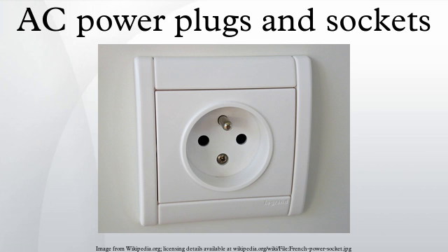Brazilian standard NBR 14136. Brazil, which had been using mostly Class II Euro plugs, and NEMA 1-15 and NEMA 5-15 standards, adopted a modified version of IEC 60906-1 as the national standard in 1998 under specification NBR 14136. These are used for both 220-volt and 110-volt regions of the country.